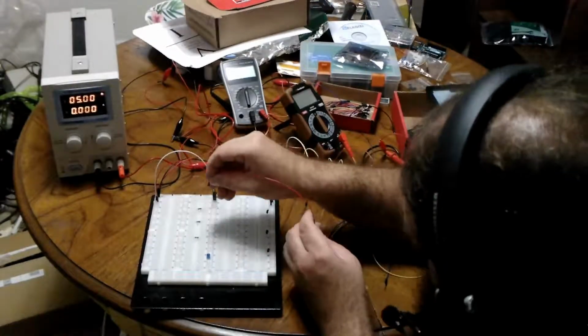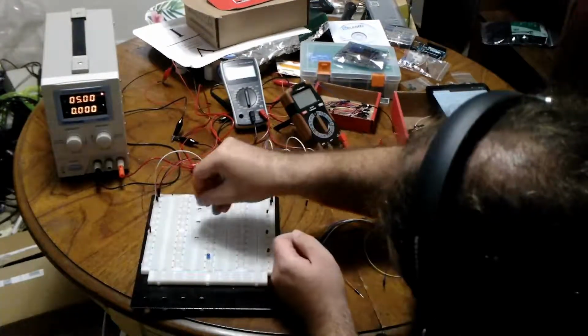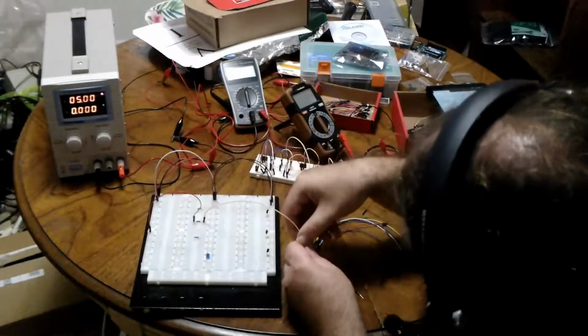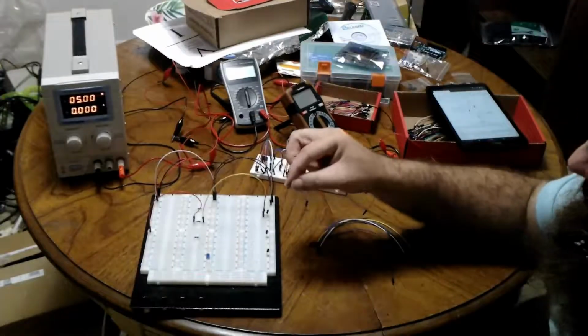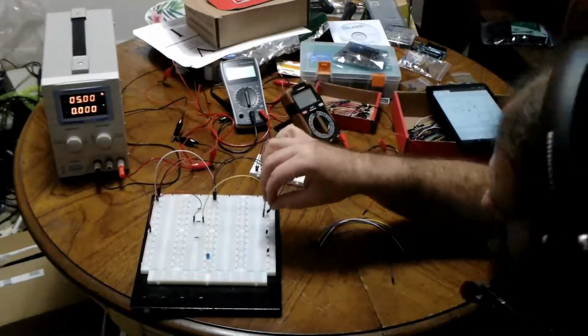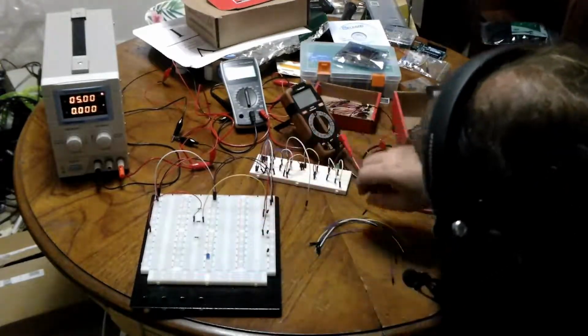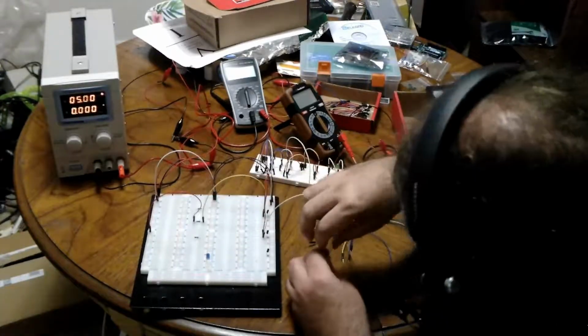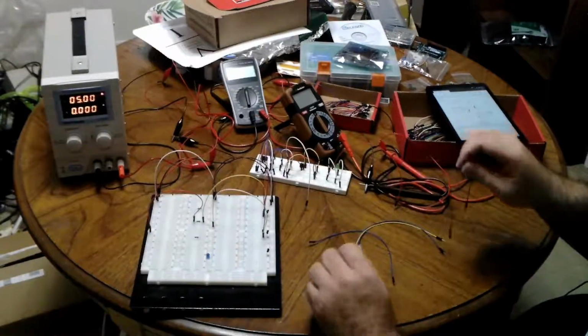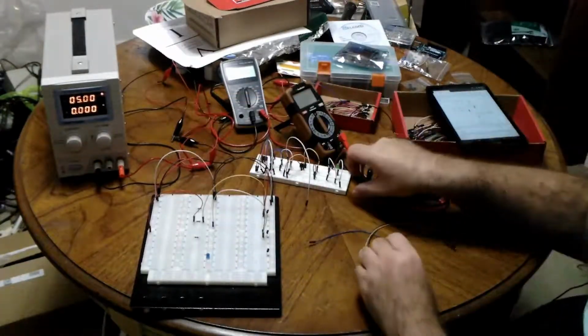Funny that. So we have our positive power to our resistor. The resistor going through the first transistor, we're wiring these in series now. And then, of course, if I connected this to negative power, we'd have a NOT gate. But if I connected to the second transistor, we have a NAND gate. Output of the second transistor, the emitter, over to negative power. And we're measuring from, well, let me put my inputs in first.